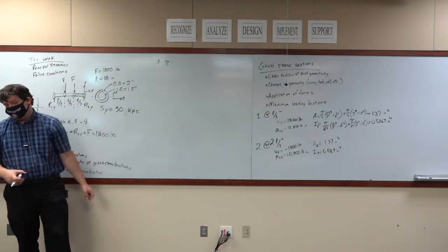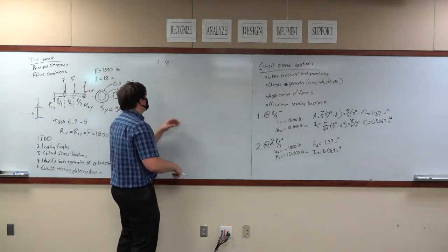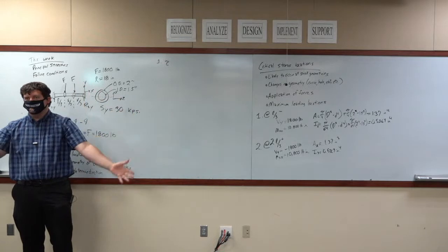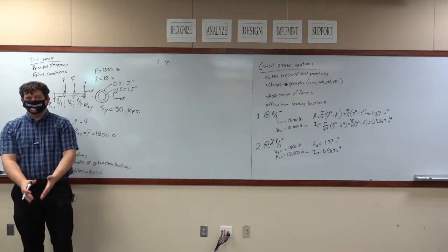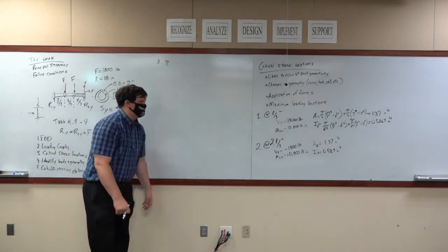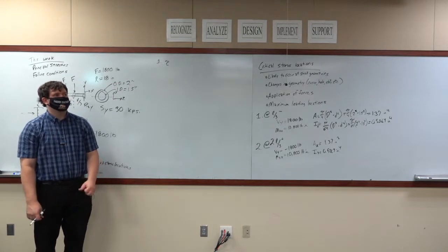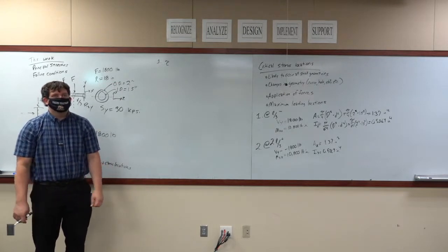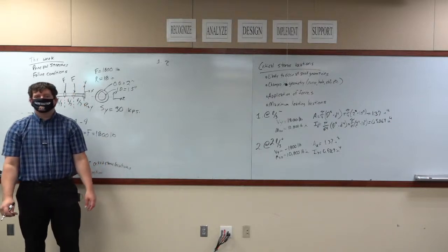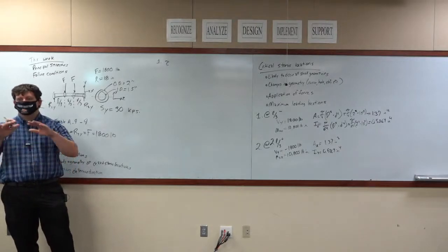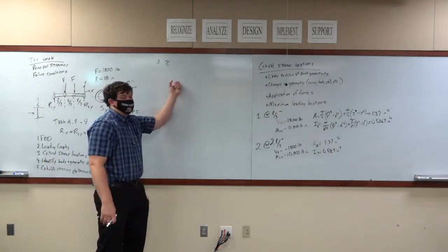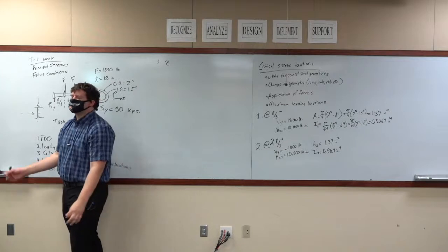So, this is a tau because it's deformation. All shear stresses are taus. All of them. Any stress that's caused by shear force is a tau. Okay? Now there's a caveat on there, but ignore that. There are some normal stresses that are caused by shear stress applications, but they're small enough that we ignore them. Okay. What direction is this shear stress going to be in?